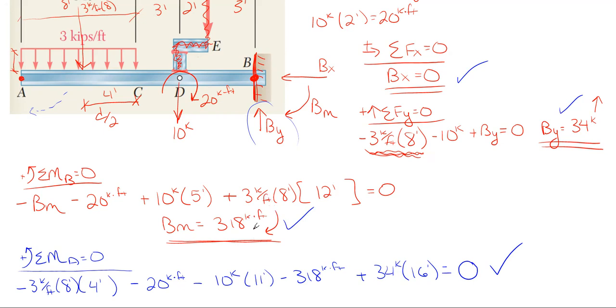So just keep in mind, whenever you are doing reactions, you can always check by summing moments at a different point, and this would be very useful if you have a test, homework, or a final exam.